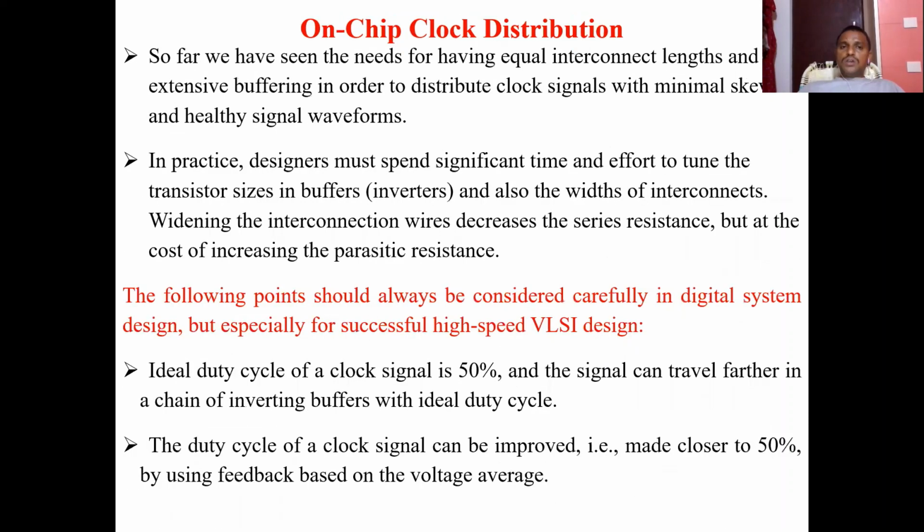Now, so far we have seen the need for having equal interconnect lengths and extensive buffering in order to distribute clock signals with minimal skew and healthy signal waveforms.